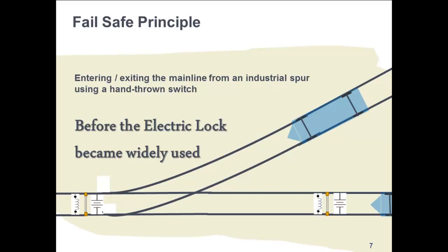What are the problems with the padlock method, Dick? Well, with a padlock, the number one problem is that there is nothing to prevent trained personnel from throwing a switch that, due to misunderstandings, allows a train, which happens to be passing through at speed, to derail. The second problem is that through vandalism, padlocks can be broken and then anybody can throw the switch. This has happened on occasion with absolutely disastrous results, or near misses, as the case may be. So the electric lock avoids these potential situations.